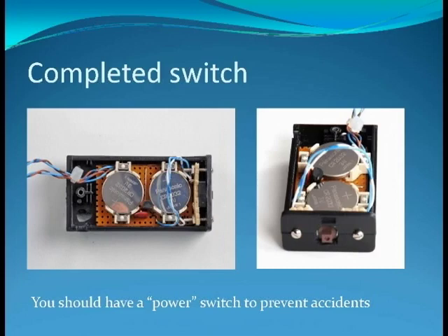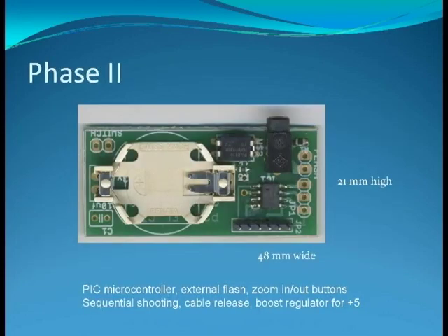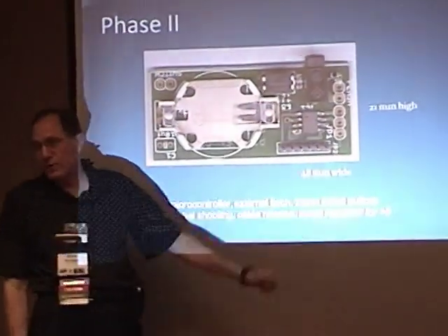Now, me being me, this is phase 2. This is laying on my workbench at home waiting for me to do the programming on it. It uses a lithium coin cell. It has what's called a boost buck regulator, meaning it regulates the voltage down until it gets below 5 volts, and then it starts regulating the voltage up to get the most battery life. It has a microprocessor running it,